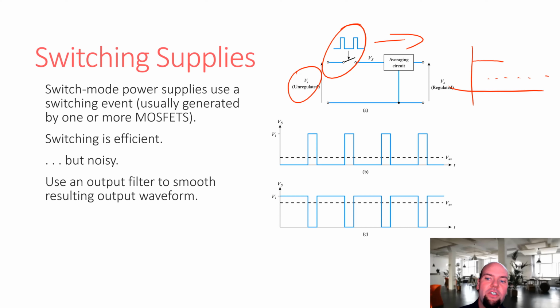An inductor is a big coil of wire, and it's going to radiate electromagnetic flux. It's going to interfere with traces on your board and with other nearby wires. So long story short, noise is more than just signal noise. It's also environmental noise. It interferes with other signals in your design.